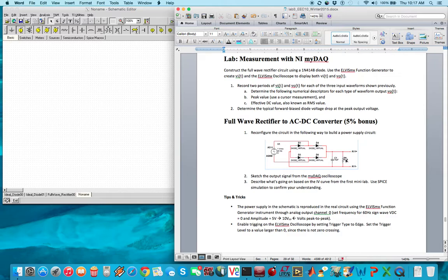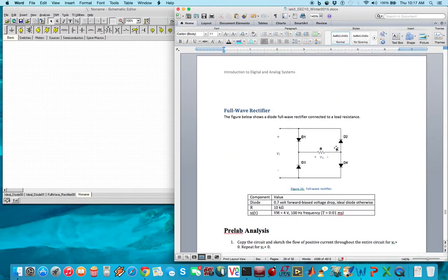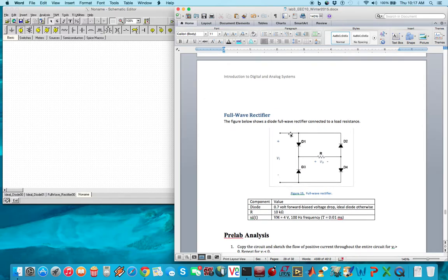resistor on the output load here. So basically what's happening is this is low passing it. In the example that we're doing, this doesn't do a particularly good job of low passing it, so we have fairly high ripple, which you'll see here in a little bit. What you should have seen when you did the full wave rectifier circuit is